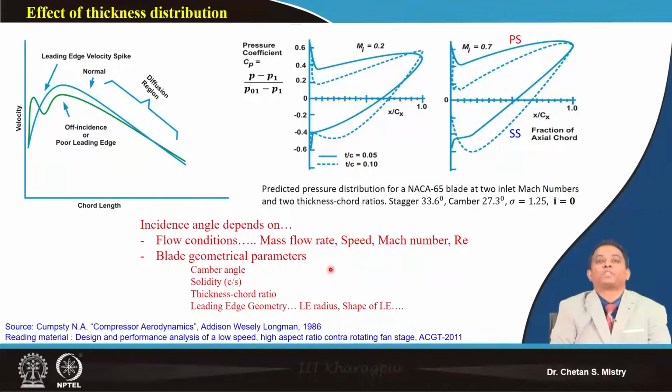Just remember, suppose I am changing my axial velocity, and that is increasing my incidence angle. But by default we have given a negative incidence angle near the tip region, so that will lead it to work under design condition even though it is working under off design condition. We will be discussing this when we discuss the design aspects. Okay, this is very important.